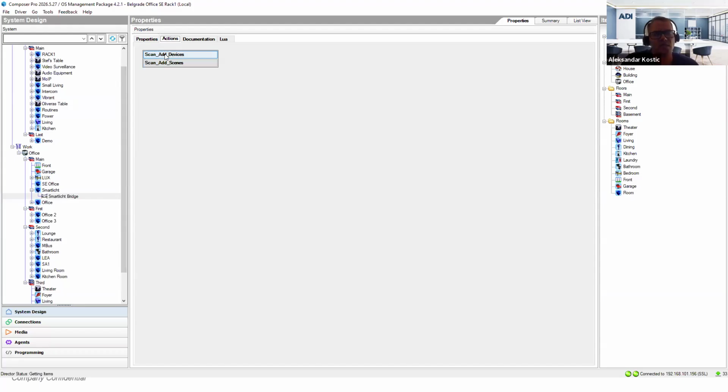So when you click Add Devices, all devices discovered on the DALI bus by the gateway will be automatically populated as drivers in the Control4 project. Also, within the web interface of this DALI gateway, you can create rooms, so you can group your devices per room. Any room organization which you create within the web interface will also be automatically imported into Control4. So it will also add the rooms and the corresponding lights within the rooms. So as you can see, it's quite straightforward.